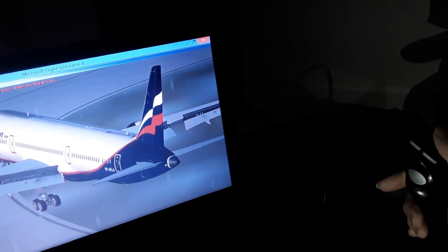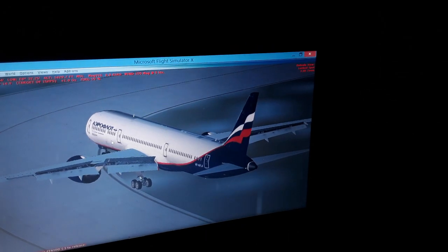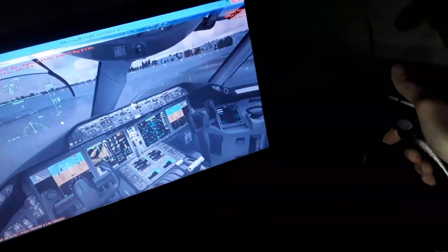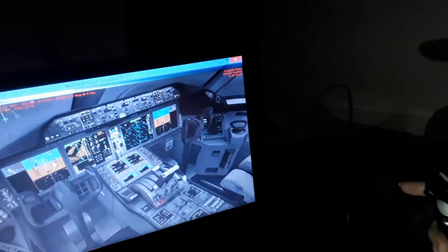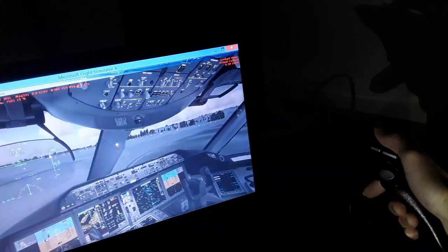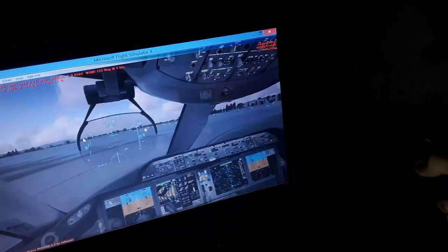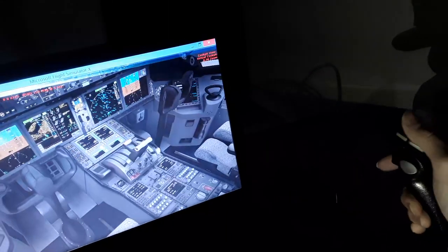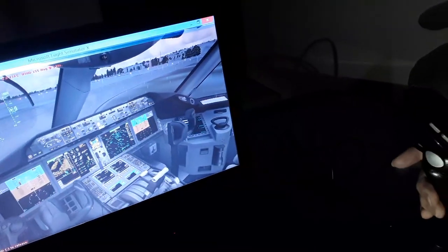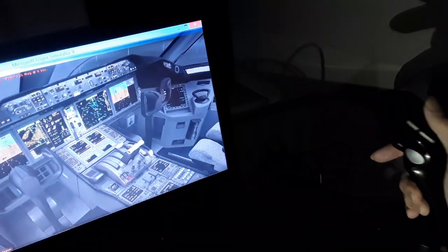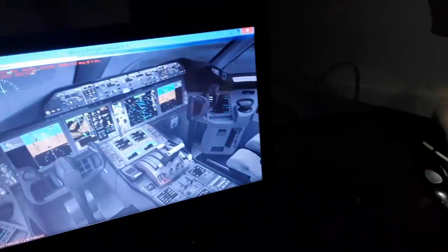Also in the Boeing we have the yoke back and forth. So this is the elevator for climb and descent, the pitch axis. Side stick back and forth in the Airbus is the yoke back and forth in the Boeing. Same flight control principle, no difference at all. You take the weight of the aircraft up, and you take the weight of the aircraft down with the Boeing or the Airbus, and you climb or you descend using the elevator of the horizontal tail of the aircraft over here, as you can see. So this is the horizontal tail.